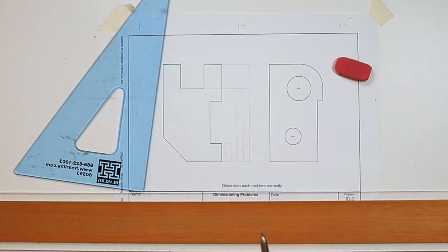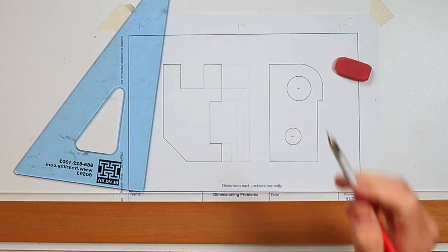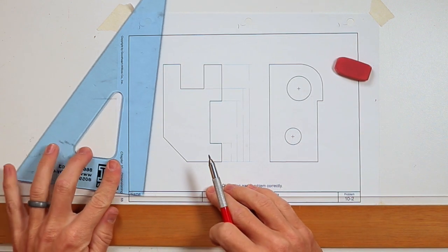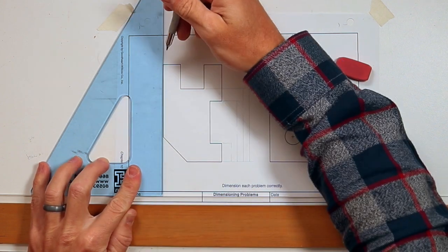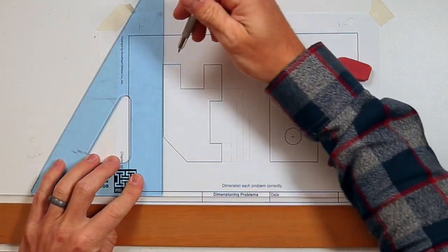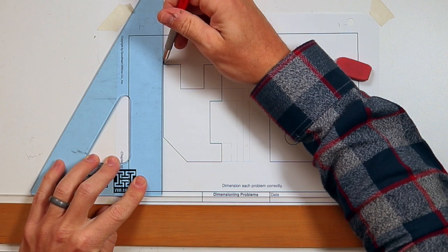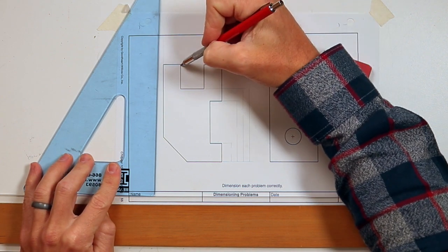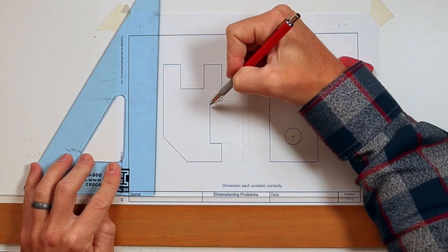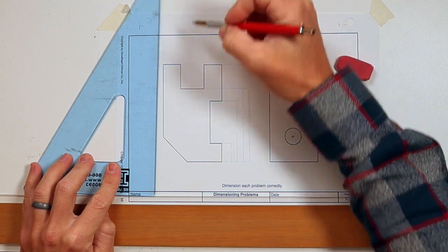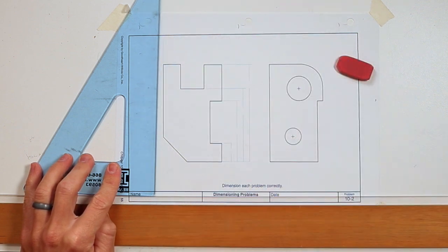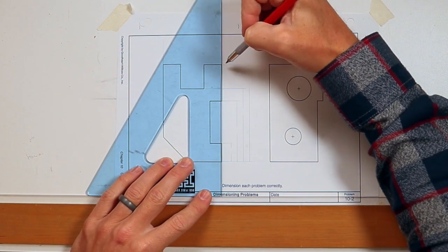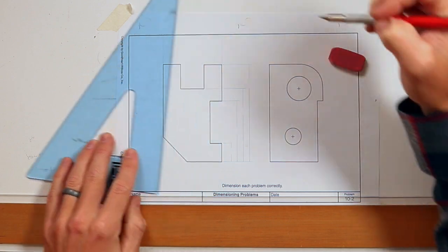Before I put my numbers and arrowheads in, I'm going to go ahead and start to lay out the top or the width dimensions. So that first extension line, I'll just extend up beyond my part. Make sure your T-square is flush against your board. And I'm going to extend up. I know I'm going to have 1, 2, 3, 4 dimensions at the top, and I'll put the angle ordinate dimension at the bottom. So I'm going to go and put the overalls in first.